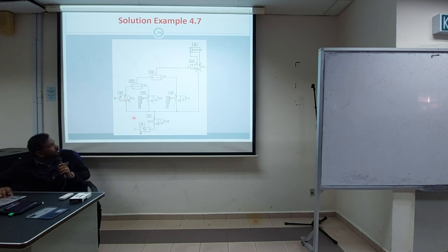If this one is on, this one is off, this one is on, it will not give a signal here, because it's an end valve. Both inputs must be given. If the 3 conditions are met, then it sends a signal here. This will change, and your cylinder will extend.